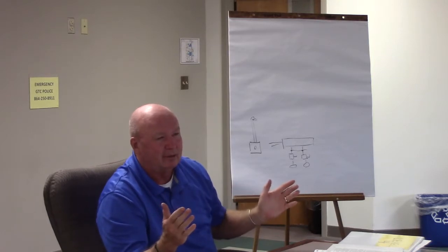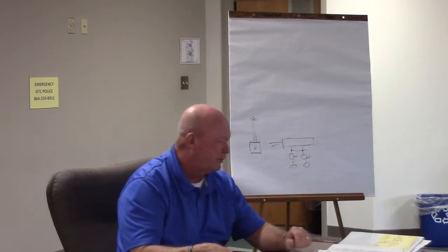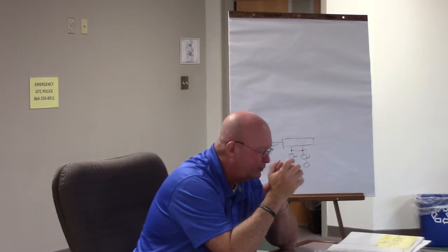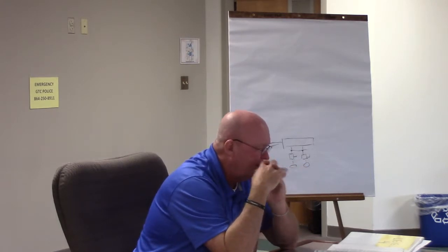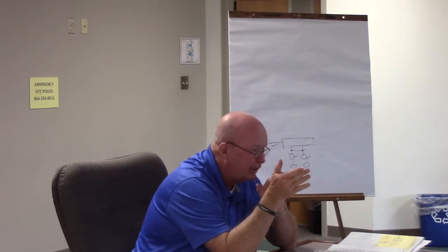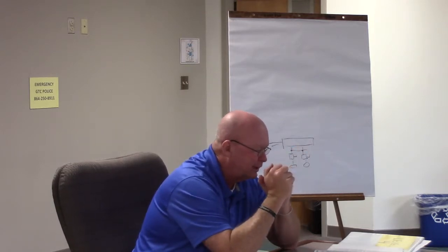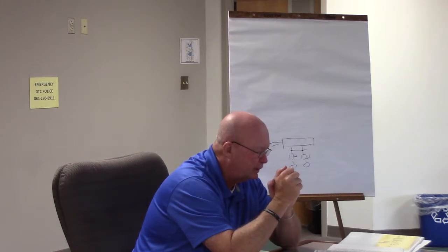So it doesn't allow you but 30 more foot. And you see that where we read it there. I mean, it just makes sense. It says use of the 100-foot tap rule is limited to installations in high bay manufacturing buildings over 35 foot. And most of the warehouses we do are right at that. It's not over 35 foot. It's actually 35 or a little bit below. 30 to 35 is generally the area that we work in more.